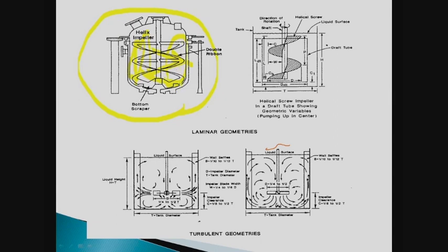The only problem I ever had with it is I think we were pumping down. It causes solid impaction, and we bent the shaft, or we bent the ribbon. We were astonished. I mean, there was a lot of steel in that impeller. But this would be a three-dimensional mixer. Lots of good advantages to it.